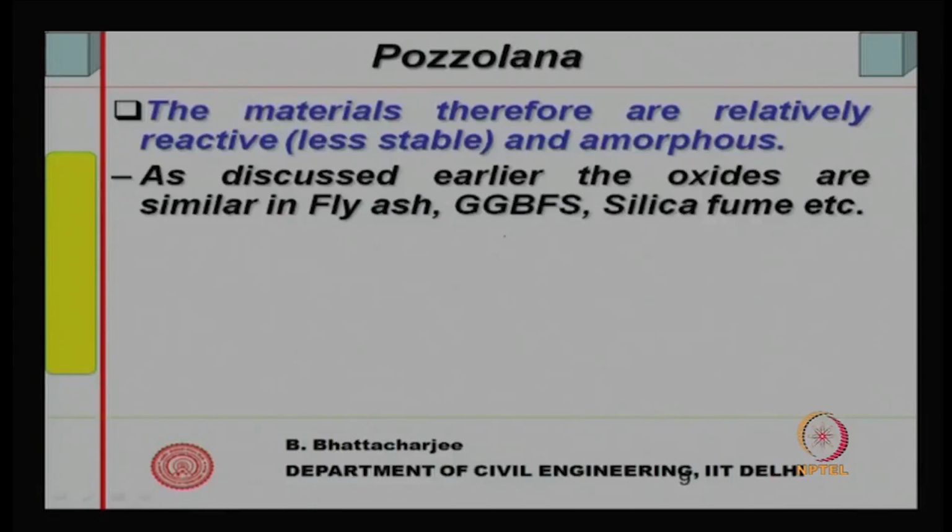So, the oxides present would be SiO2, Al2O3, in some cases a little bit of calcium oxide and in other cases more, right. For example, in this case it is high, but I have not come to the production of this as yet. So this case has high calcium oxide, and some fly ash has a high lime content.